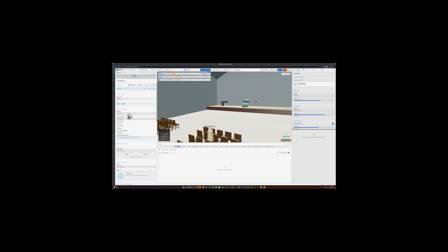Next, let's define the sound source. Choose a source from the list. For this demo, we'll use a preset acoustic source. Because we're using a voice sample, it's worth spending a moment on radiation and directivity. Human voice is not truly omnidirectional. Most of the energy projects forward, and that directionality becomes more noticeable as frequency increases. So we'll choose a forward-weighted radiation setting and orient it in the direction the speaker would naturally face.